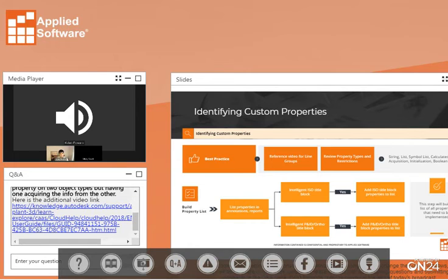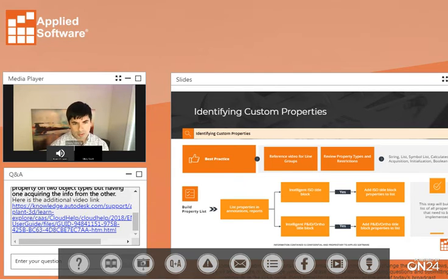Yeah, so this is really about, as far as the stage of developing your project template goes, you need to sit down and figure out where to start, right? Because we have, let's say, 100 PIDs. Well, what's the starting point? So you need to pick a sample of your PIDs, and go through and identify what shows up in any of your text in your drawings. And you'll get a sample of your reports, line list, equipment list, and identify the properties that show up in those reports.